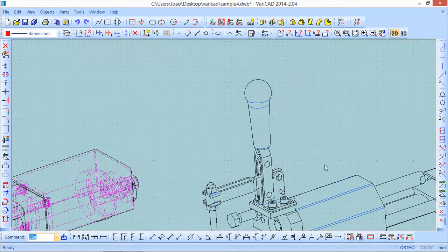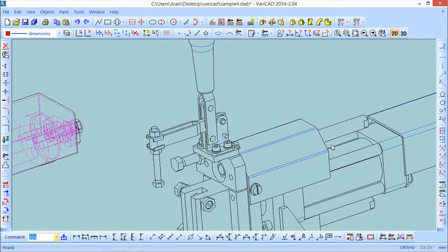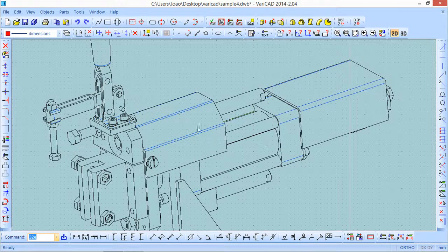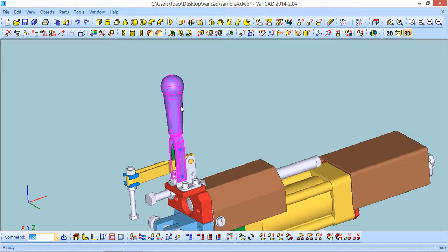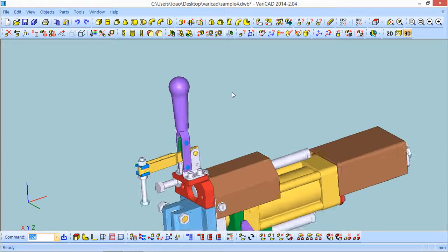These are important to define my object, like these fillets here. If I go to the 3D, you see that this is a tangent, especially the fillets. If it is tangent, the lines will not be present on the 2D, and we should have them for better understanding. Okay.